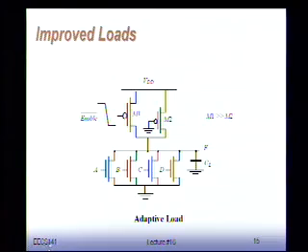I'm going to transition from one to the other one. I want to have a small resistor there that's really going to be helpful for everything. However, from a noise margin and a static power dissipation perspective, I would like to have the PMOS as small as possible, meaning large resistance, because then I get a very small VOL and very small power dissipation.